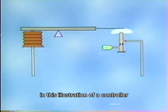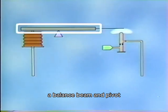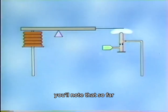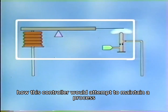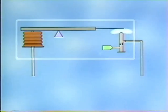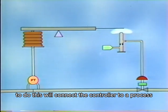In this illustration of a controller, you'll recognize some of the components we've been looking at, including an input bellows, a balance beam and pivot, and a flapper nozzle arrangement. You'll note that so far, the controller in this illustration does not have an output balancing mechanism. Let's see how this controller would attempt to maintain a process variable. First, without an output balancing mechanism. This will help us identify why output balancing mechanisms are needed. To do this, we'll connect the controller to a process.